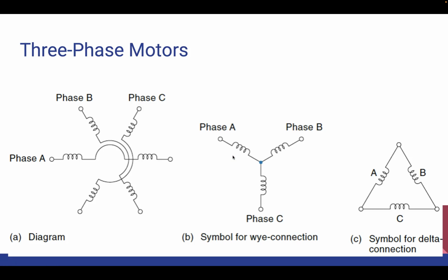Now this is the diagram for the three-phase motor. A three-phase motor is simpler and smaller than its single-phase counterparts, but it can be used only where three-phase power is available. Usually this is used in industrial sites, therefore motors tend to be from 2 horsepower and up.